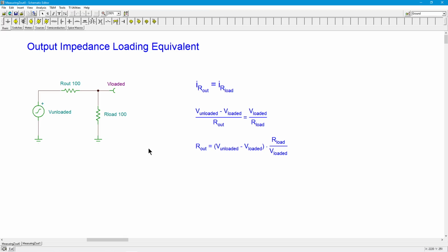Now, you can spend money and get some really nice meters. We have some really nice meters in our lab that go up to either 50 or 100 kilohertz, I forget which. Those are our true RMS reading multimeters, but of course, they were hundreds of dollars a pop. A scope, however, doesn't have that kind of limitation. A scope has a really, really wide bandwidth. So the only difference there is, instead of reading an RMS voltage conveniently in digital form, you're going to have to read it as a peak value.